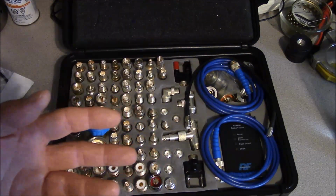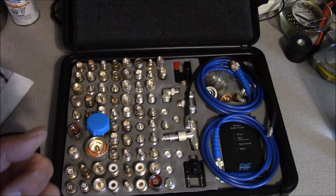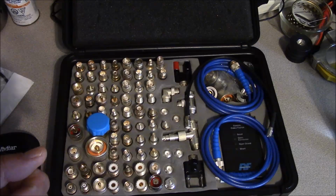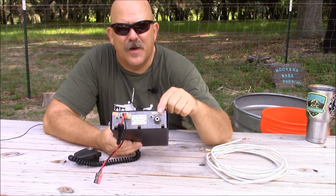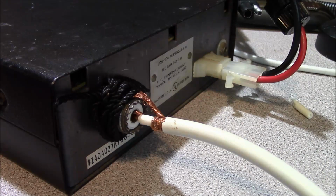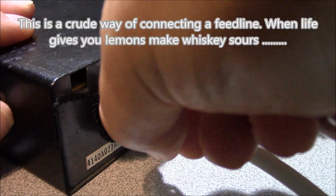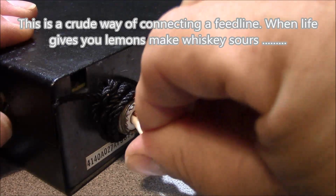Now, failing the ability to gather any of the resources outlined above, we end up having to use an emergency attachment method shown here. And much like the phone company, if it touches, it talks. Just break your two coax conductors out. You can fold back your center conductor on itself to take up the space.